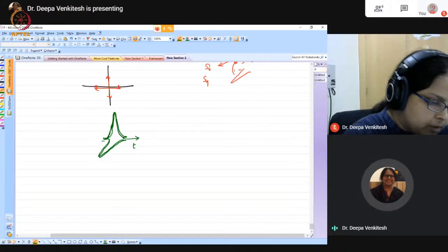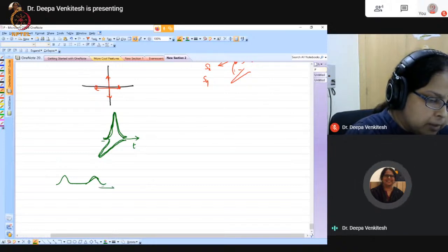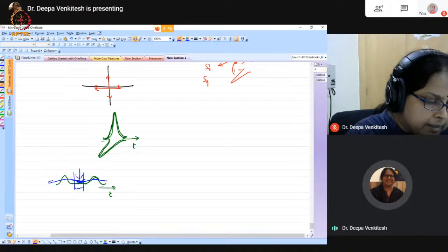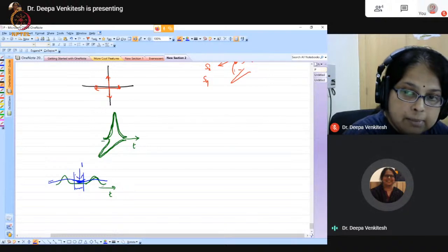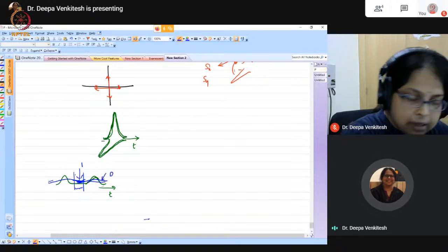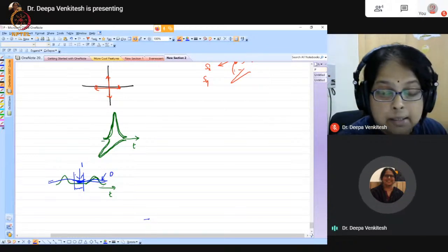So how did we understand chromatic dispersion? We understood chromatic dispersion by saying that I have a bit which is like this, and as a result of the chromatic dispersion, the consequence in the time domain is that the bit started broadening, like this. And when it started broadening, for example, in this particular slot, if there is sufficient energy, I might demodulate by mistake that this is 1. And I might demodulate this as 0 if the dispersion completely flattened the pulse. That's how I understand chromatic dispersion.